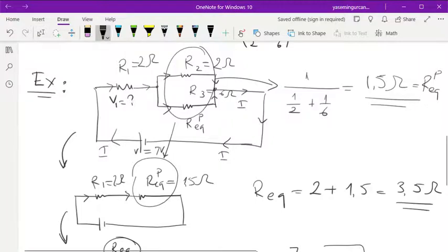So for this part of the circuit, again, V is equal to IR. And again, I'm telling you that Ohm's law can be applied on a single part, like one unit of the circuit, like R1 itself, or for the whole circuit or part of the circuit. Ohm's law holds for each and every resistor that you can think of. So you can apply it to R1 separately.